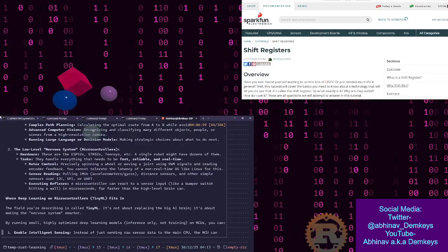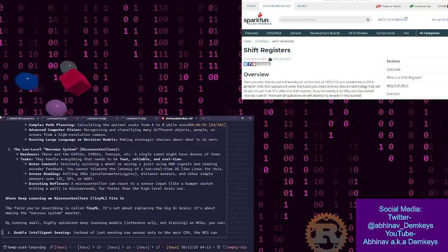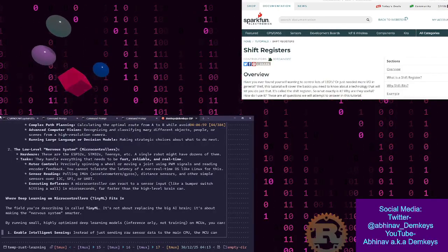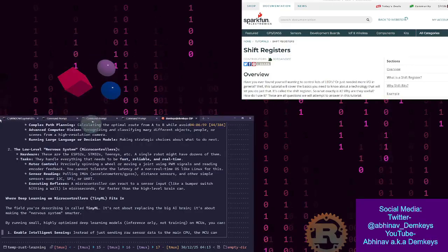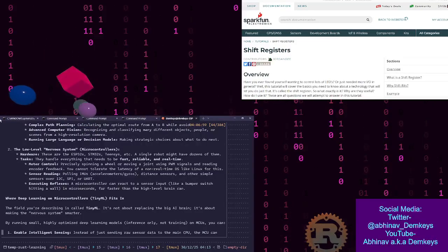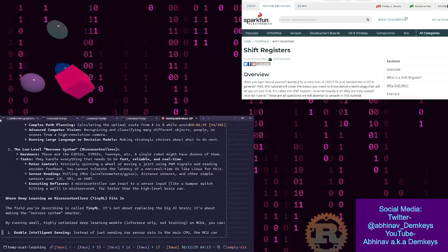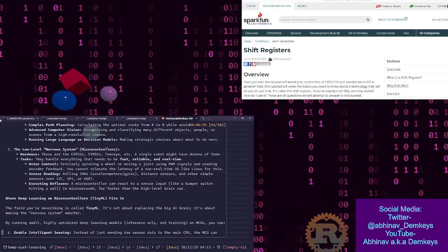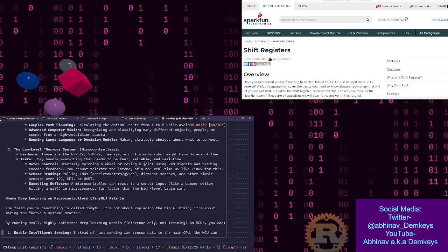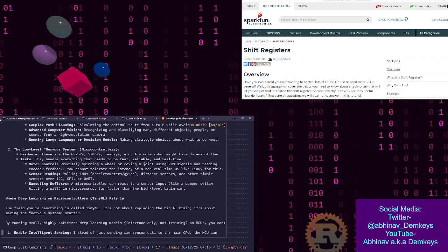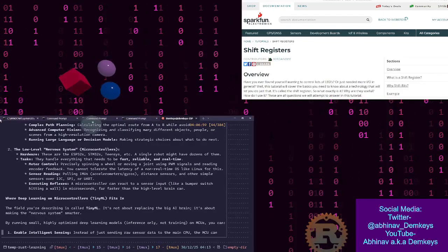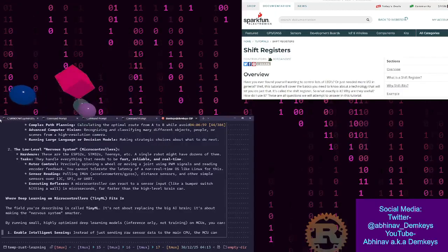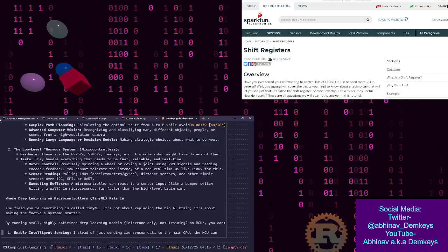It is possible to program the ATtiny85 microcontroller using Rust, primarily through the community maintained AVR HAL and AVR device crates. This requires a specific development environment setup and is considered a more advanced bare metal approach compared to the standard C/Arduino method.